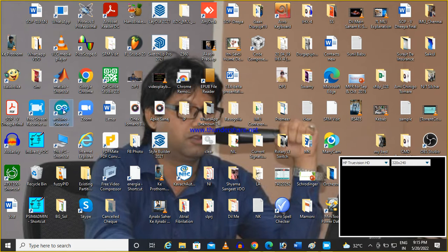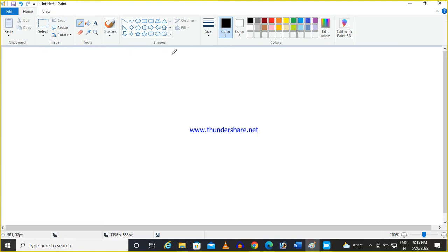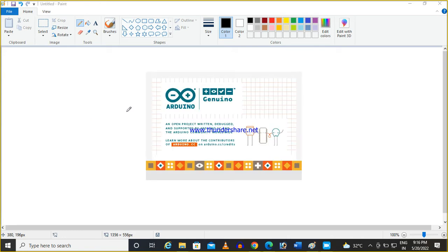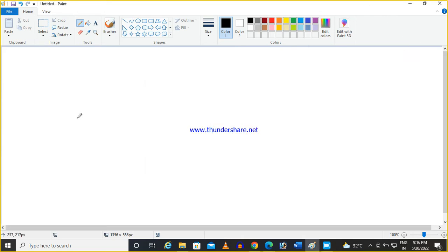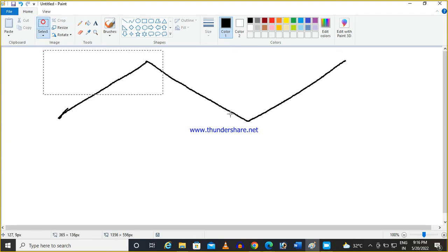now we will discuss about the PWM. So in PWM, basically we are going to generate it through some timer. Timer is a very important component in microcontroller, which is used for several purposes. So the timer, what it is doing, it is counting from one value to its maximum top value, and again it is coming to 0, then again going, it is counting like that only.